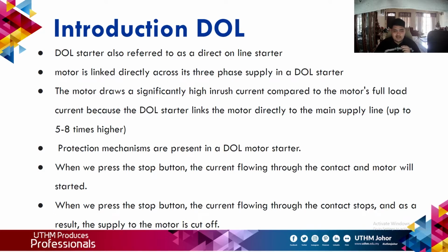However, with this high inrush current, there are also protection mechanisms in the DOL motor starter, such as the circuit breaker or miniature circuit breaker and the overload relay.